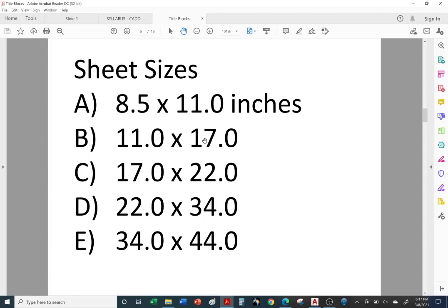So now the next sheet size is 17 by double the small number, 11 times 2, 22. Now we have 22, right? For D size, you go 22 diagonally across, 22. And 34 is just double 17. 2 times 17, 34. And for an E size, take the 34 diagonally. So it's a 34 by 44. 44 is just double 22.